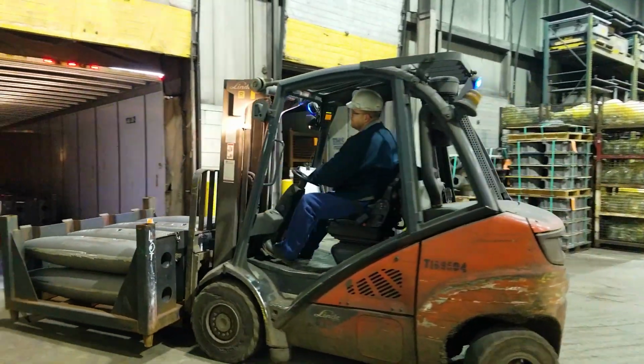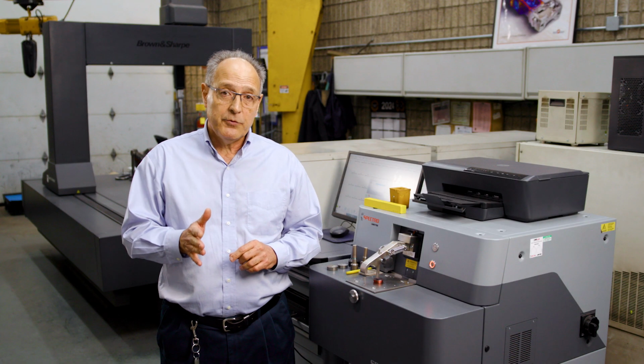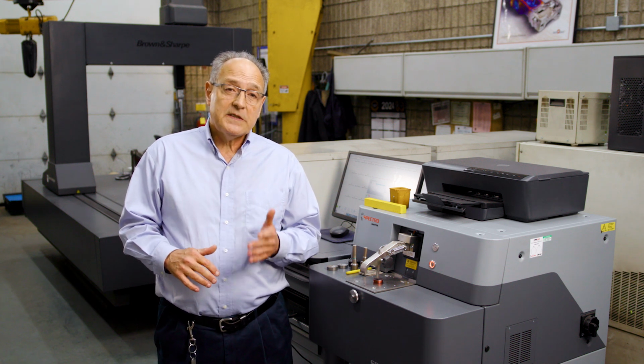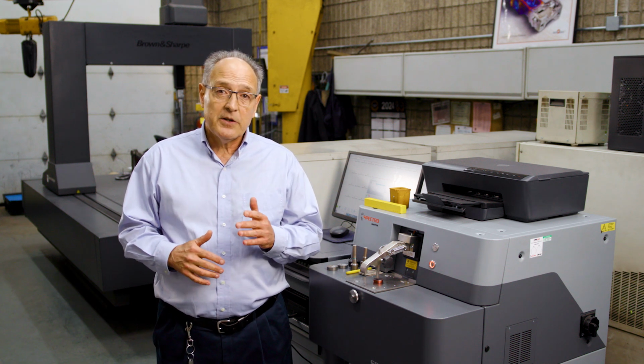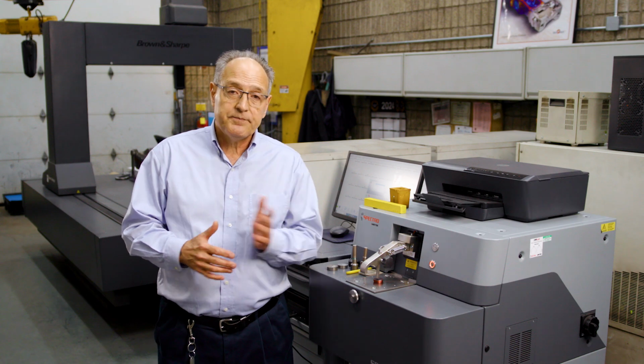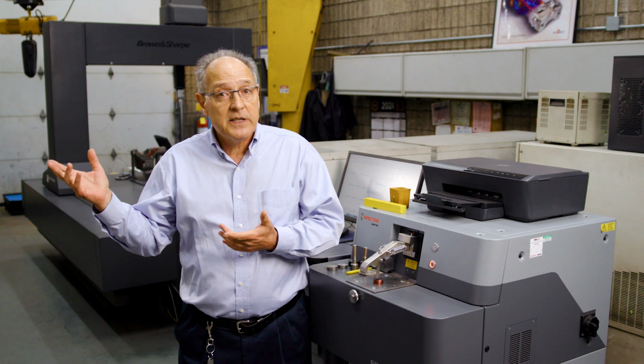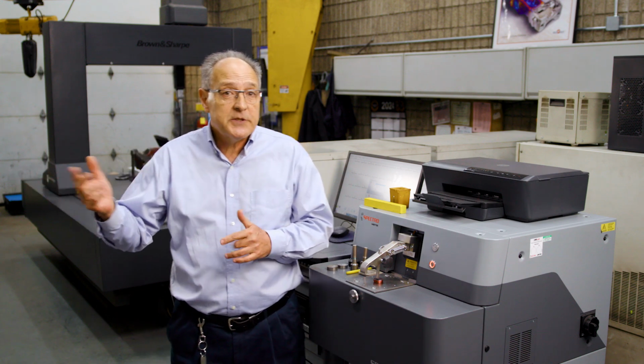The definition of cast iron is an iron carbon alloy with more than 2% carbon. And I need to compare with steel. What's the definition of steel? Iron carbon alloy with less than 2% carbon. So most of the steels actually have 1% carbon or less. If you want a drill bit or a bearing that's very hard, you have about 1% carbon, and that carbon is going to create what's called carbides. Well, in cast iron, you have a lot more carbon than that, 3.4, 3.8%. That should be harder. However, it's not.